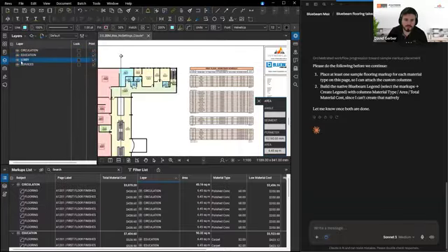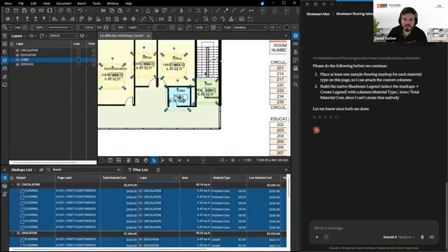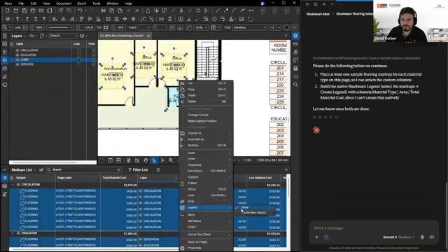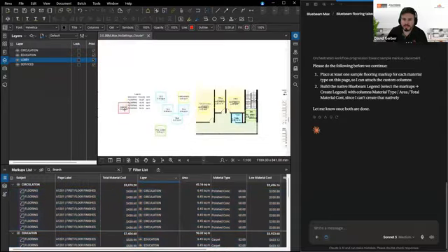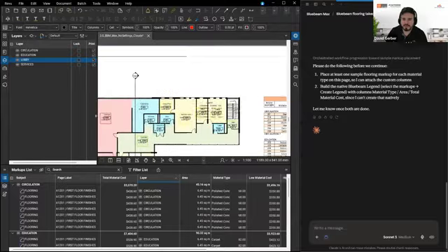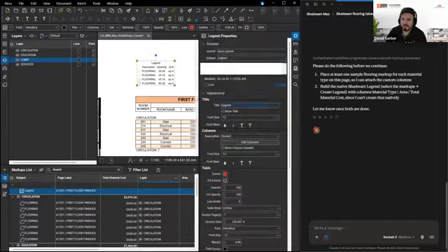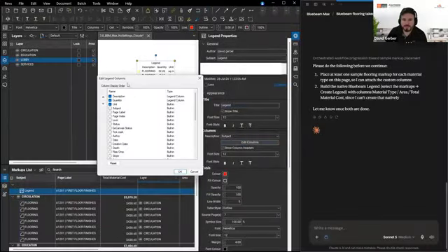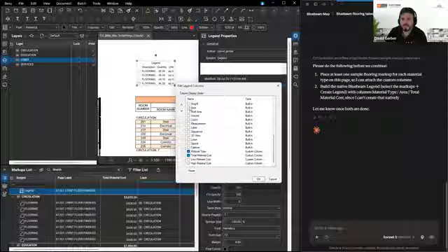And if I just turn on all of them, I can just hit Control A. So I can select all of them, and then I could just right click and create my legend because maybe we need one. So you can see that here. I'm just essentially going to try and match what came from Revit, like the colors, and just put it here. You can pick and choose what's in your legend as well, even your custom columns that you made. So maybe we don't need that quantity, but we'll go through maybe the total cost, material, and its area.